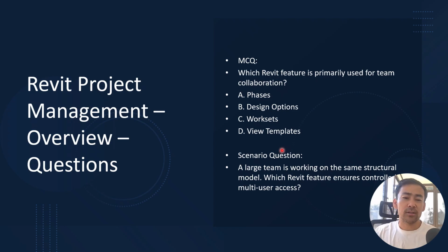So first, the worksets are defined and each person can borrow elements from a particular workset, and once he or she is done, then she can relinquish the work, the design, to communicate and share with others. He can also comment on that. So we will show how it works in Revit.